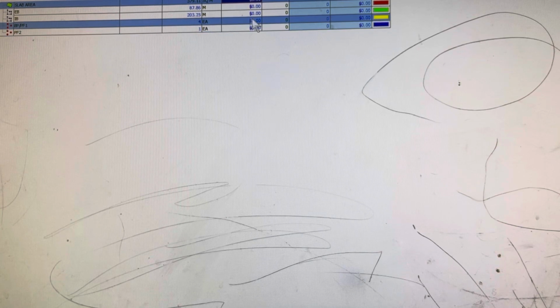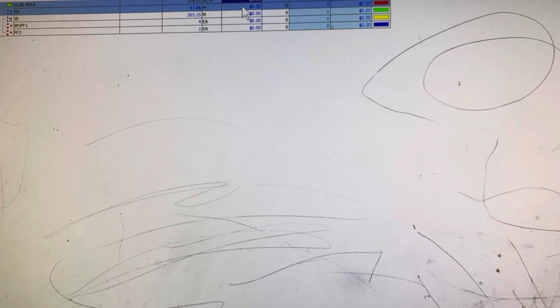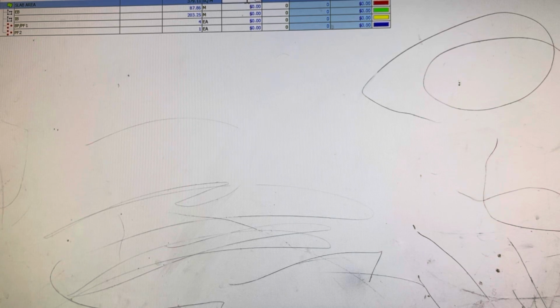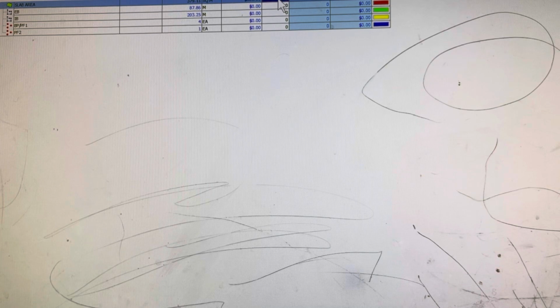Now if you say, from past experience, the cost was like $300 per square meter, let's put the square meter cost, 300. So it's giving you a cost of 113,733. Now you want to put some markup, like 15% markup.